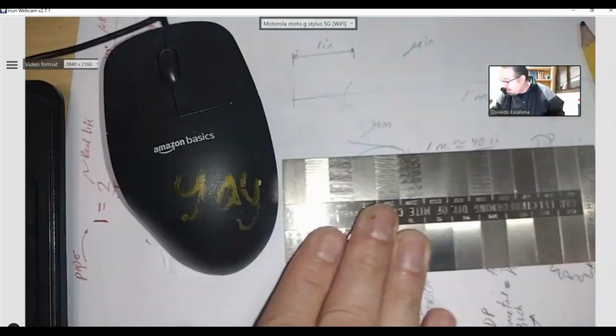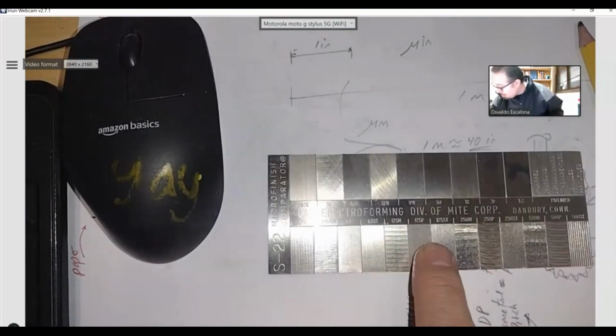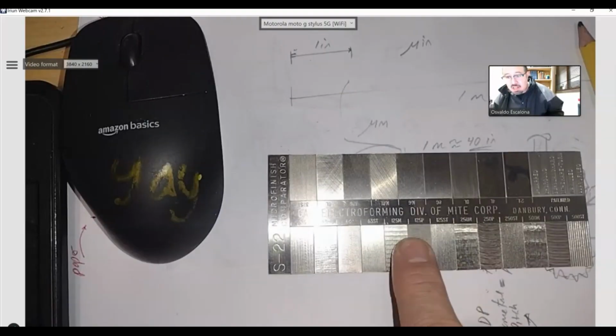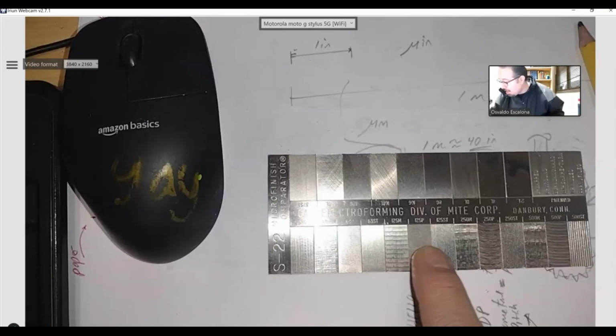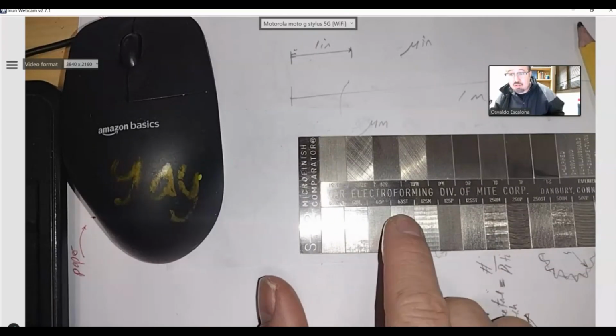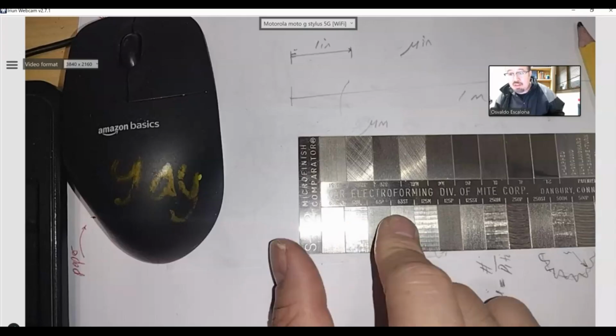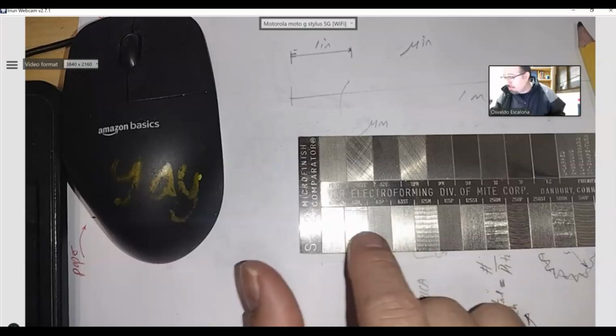So I went from 125, right? Which this 125 I can achieve with pretty much any milling operation or any turning operation. And I grab into the 63s. The 63s, again, I'm still not going to use it for finishing up for moving high rotating parts. Right, so I'm going to skip this one. If I want a nice finish with a rotating part, it will be this one.